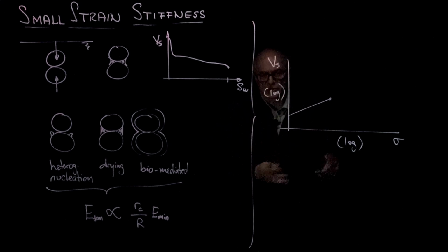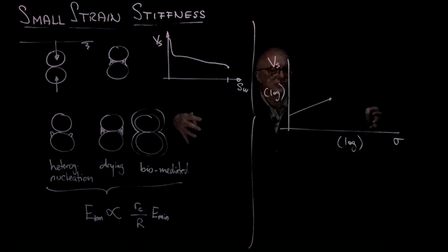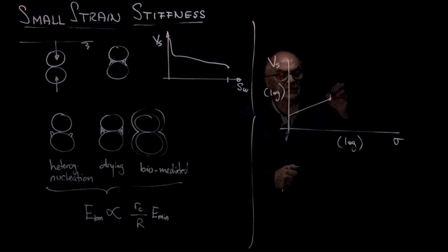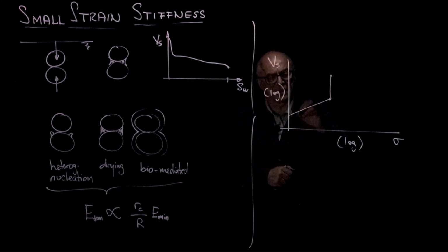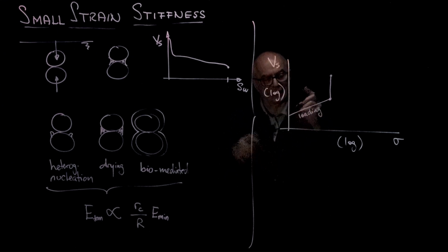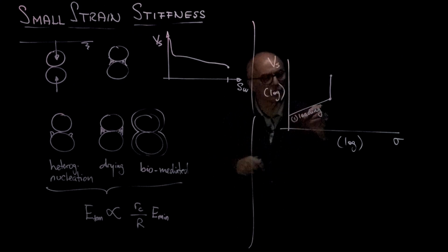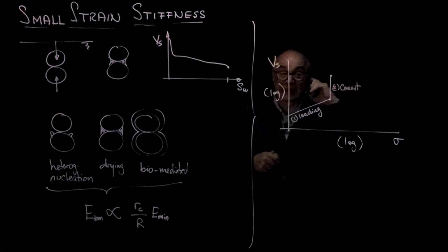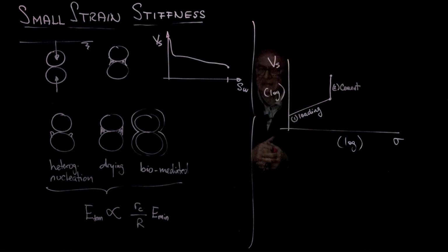Or we have put some cementing agent. Or we're running reactive fluids that will precipitate cement. And we're going to see a very significant increase in shear stiffness because of cementation. So this is the initial loading. And notice that once again, everything is sequence dependent in this case. So this is step 1. Step 2, we have cementation. And the stiffness increases quite dramatically.